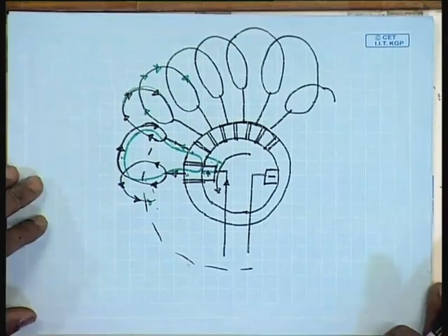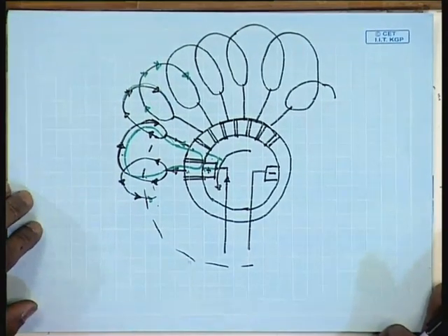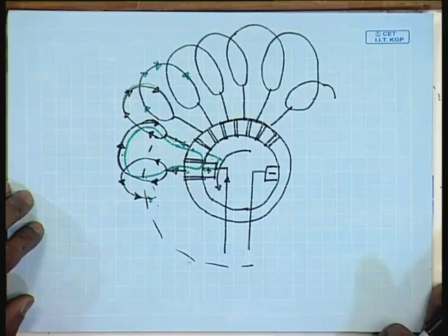Therefore, it is not possible to short this coil when there is an induced voltage. So, only those coils in which the induced voltage is 0 will undergo commutation. This is ensured by placing the brush accordingly. The brush will connect to that coil in which the induced voltage is going to be 0.